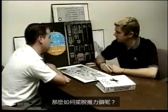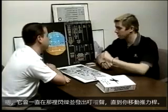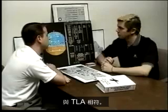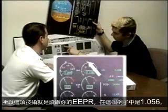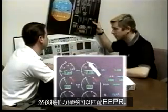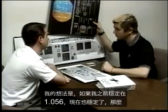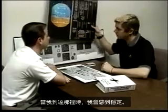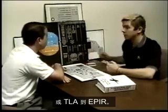How would you get rid of thrust lock then? Well, it's going to be up there flashing and dinging until you move the thrust levers. The second you move the thrust levers, the thrust is going to try to match where the TLAs are. So the technique is to read what EPR you have, in this case 1.056, and then move the thrust levers back to match that EPR. The thought being that if I was stabilized at 1.056 before and it's stable now, it's going to be stable for me when I get there. So I bring the thrust levers back and match the EPR to the TLA, or the TLA to the EPR.